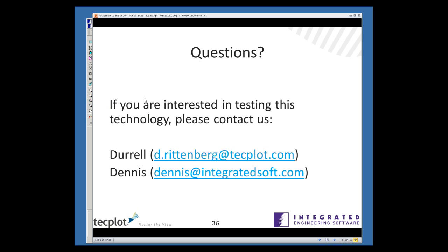Yeah, the question is about the permeability plots that I showed earlier. So that's the ratio of the B to the H field. No, we're plotting the differential permeability there. We could plot B over H, but we're actually using the slope of the BH curve. We find that gives a better indication of saturation. As I say, though, if you wanted to plot B divided by H, you can do that as well.